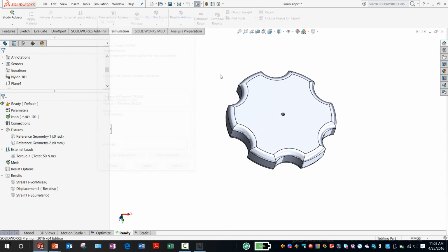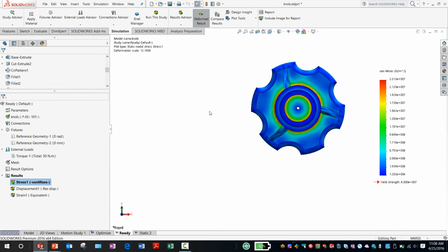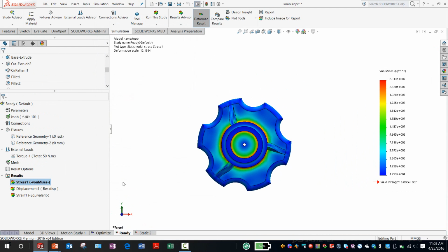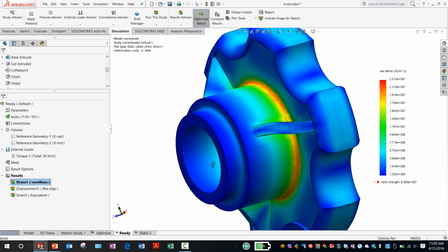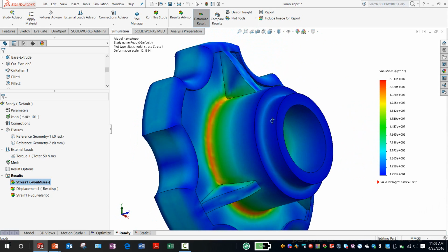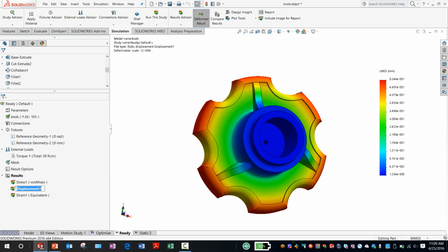Quick simulation, it goes on fast. Probably I also have a good machine maybe, but this is how it looks. So as expected, these stresses are somewhere at the joint here. Definitely there is scope for improvement of the mesh, but this is how it looks. It is not crossing the stress limits. It is fairly okay on those aspects, all good. But definitely other way around, this is also telling that it is over designed and there is scope for improvement.